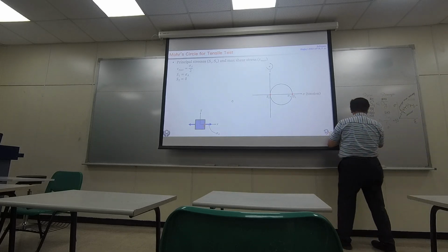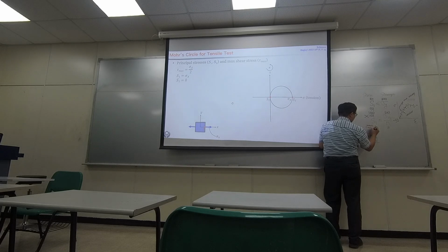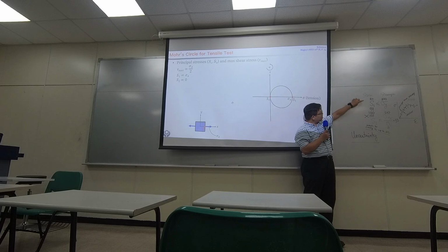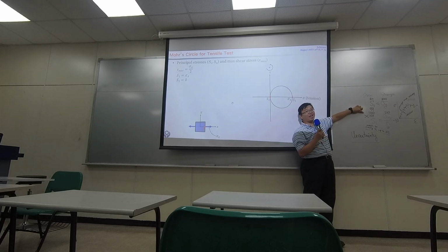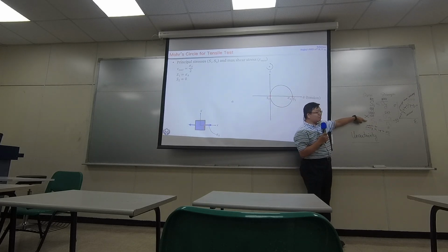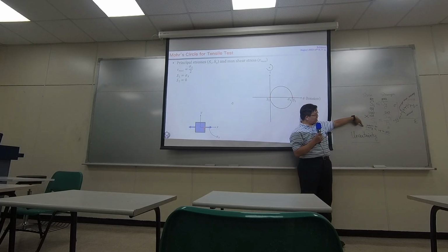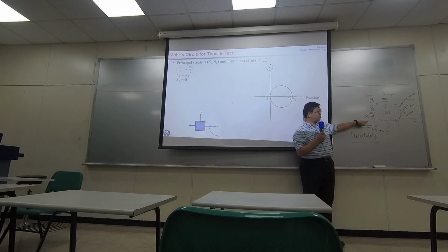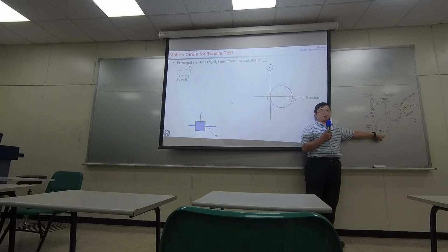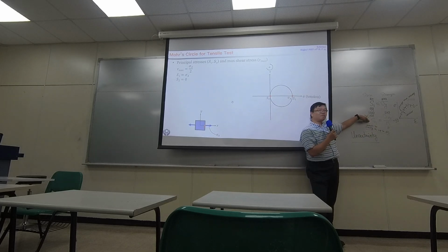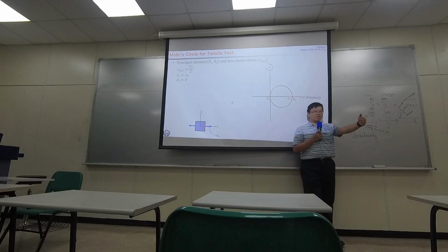You only want to carry stress up to 50 in this particular example. So compared to the first design equation, you realize you are allowing the stress to be as high as 100. But if you choose your safety factor to be 2, then you only allow your stress to be half of the yielding strength. So basically, you only allow your stress to be as low as 50, which is safe because you are having a huge gap between your max value and the yielding point.